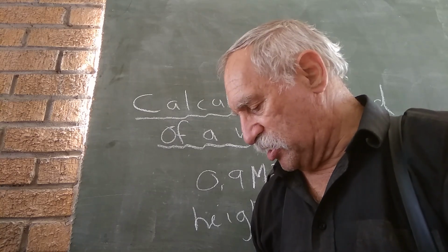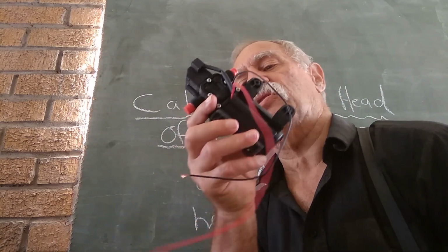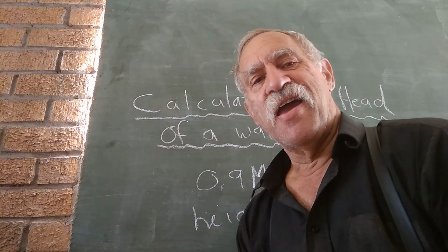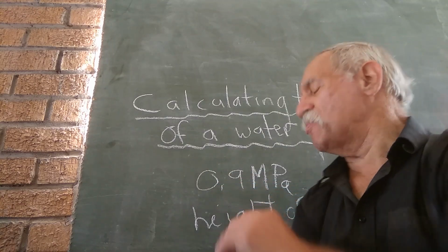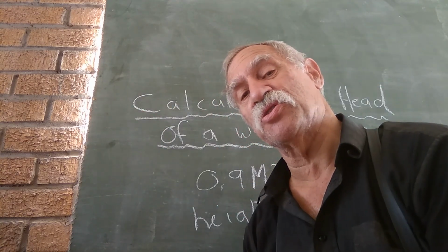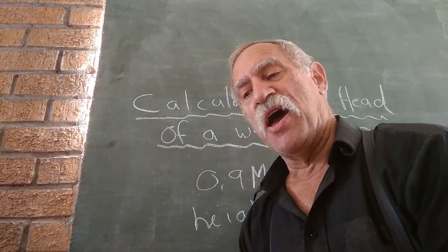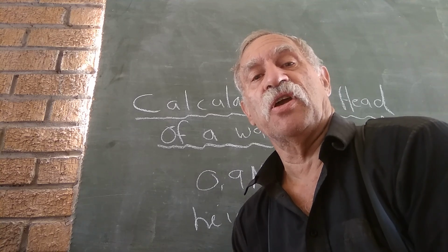And obviously 6 liters per minute, that sounds pretty reasonable. That's quite a fair flow if such a small little pump can do it. And then it'd be interesting to see, when we've converted 0.9 megapascals to an actual height that this little pump can supposedly pump the water to, let's try it out and see if it can actually pump water to any height.